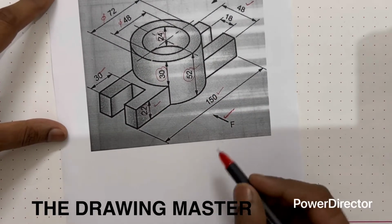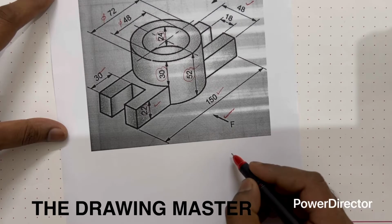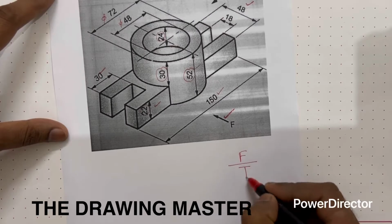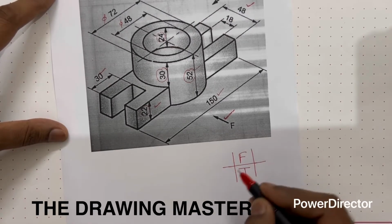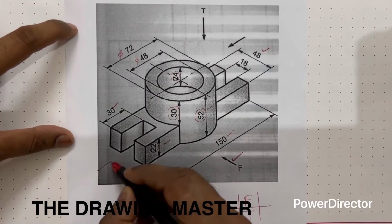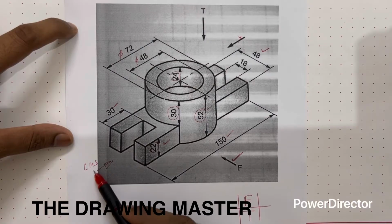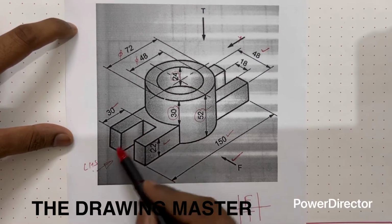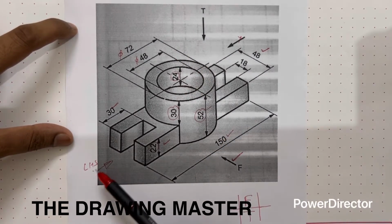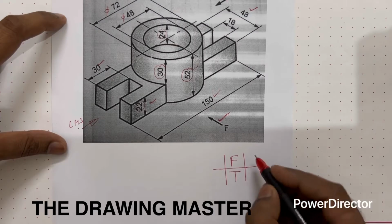So now we have to draw the front view, side view and top view. So let's decide the angle of projection. We'll draw it in first angle of projection, means this is front, this is top. So this will be the left side view. We'll ignore this. This is left hand side view because this part is visible to us. So we'll draw the left hand side view. As per first angle of projection, this is front, top and left side view will be here.